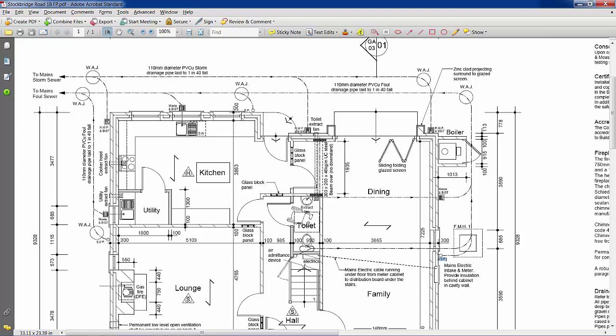Also over here at the end we have another soil vent pipe, and then we have a series of manholes and inspection chambers and things like that. So this one here is a manhole. Make sure that you draw those an appropriate size for the scenario that you're dealing with. And obviously the toilet is discharging out into that, as well as possibly something from the first floor. And then the direction of flow should be indicated on here.